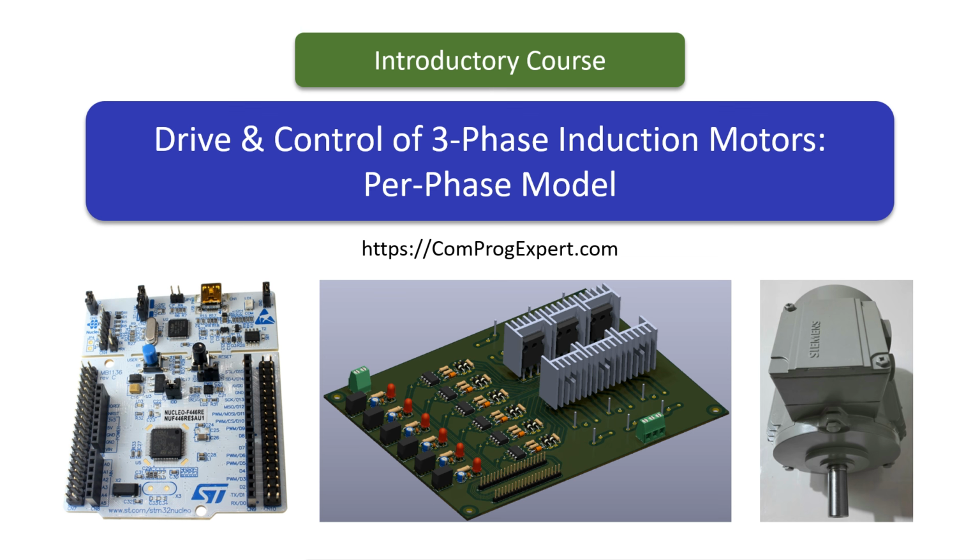As you know, we can use the per-phase equivalent circuit model of the motor to evaluate the steady-state performance. Yes, we can calculate characteristic curves such as the torque speed curve, the variation of the stator phase current versus the slip, or rotor phase current versus the slip, and so on.